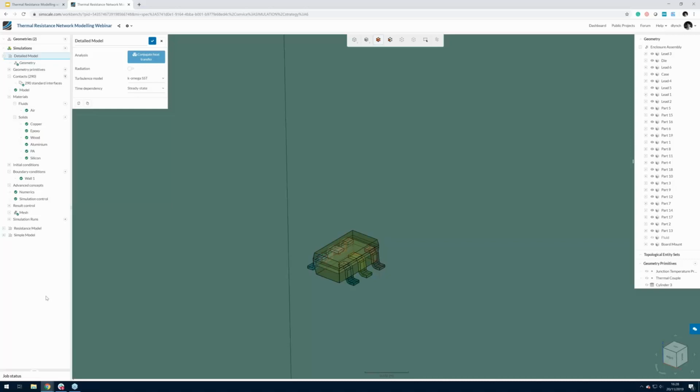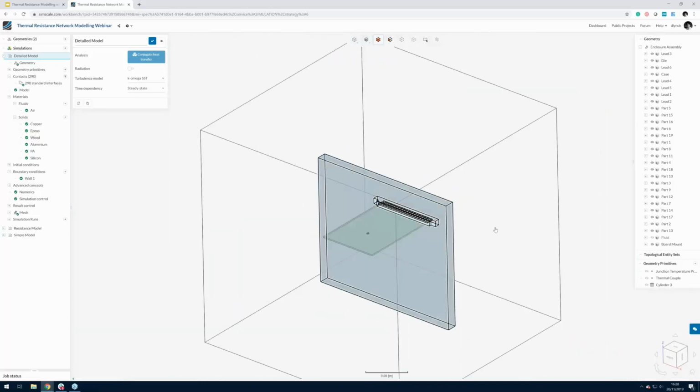The casing is not very conductive, so that is actually insulating to some degree the component, the die. So that's included, and the die is the source itself. Now, if you had more information about this component, then absolutely include it. This is only a test environment, so the idea would be that you run your simulation on this test environment, on this detailed model. You get the resistance values, and then you validate your own calculations.